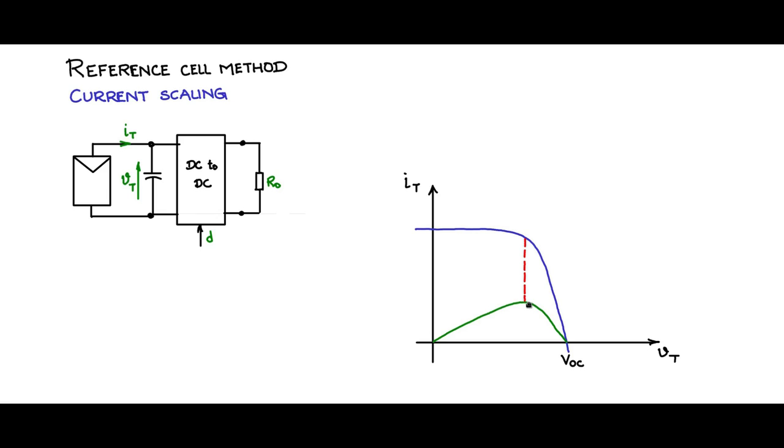So I have the peak power point, and this line intersecting the IV curve is the operating point corresponding to the peak power point. Now a line which joins up like this is the load line, 1 by RT, at which the operating point gives the maximum power.